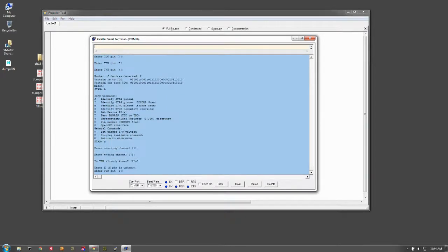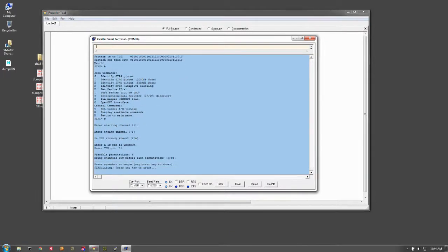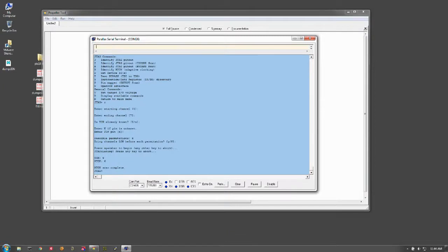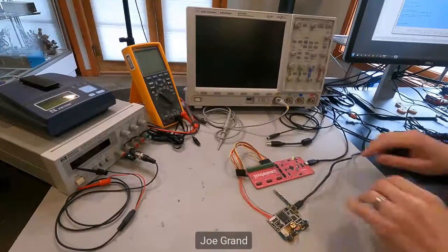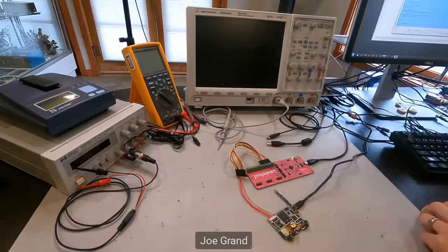Let's see, is the clock already known? It is. We just detected it as 5. It's going to check those and check for this additional return clock. And now we have all the pins that we can go and hack on a system, which is cool. So I'm going to end screen share. That is the fastest JTagulator demo I've ever given.